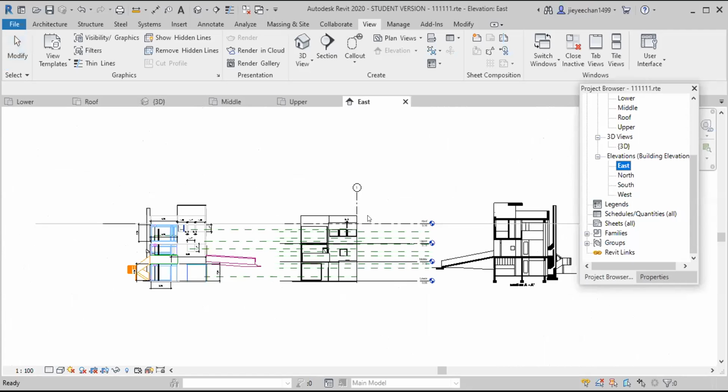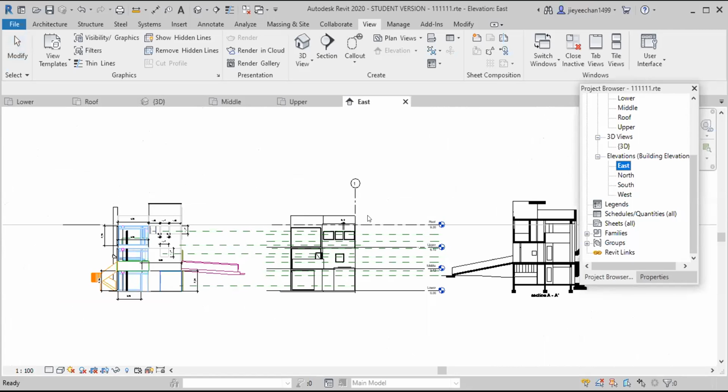Okay. Actually, you have to follow the section. You have to create an elevation with the height of the section. But you have to be careful. This one should be aligned first. They are not aligned. So you have to align this, and after that you create this elevation and call it roof 2 maybe. So this one is roof 1, the main one, and then roof 2. When you have roof 2, you can go to roof 2 and draw the shape of roof 2.